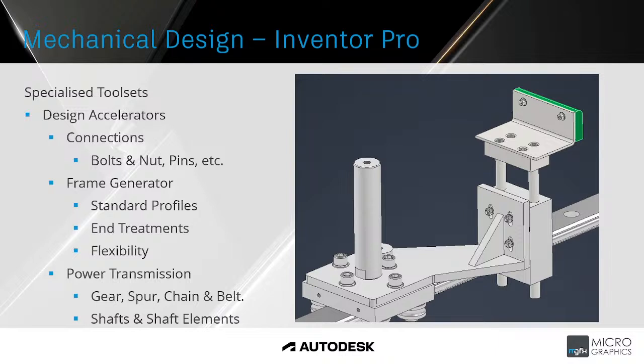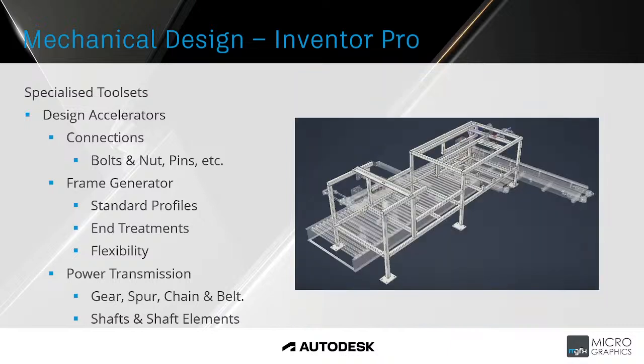And with the design accelerators, creating bolted connections like this is a process that is somewhat automated. You would go ahead and select the 4 holes where you want to place the bolts. You select your start plane, your end plane, and you then choose the hardware that should be placed in. That process of choosing the hardware can also be saved as a template. So the next time you add in a bolted connection, you can just choose the template, saves you from having to specify the hardware every time. And so it would be quick and easy to create these connections using that design accelerator. And the same goes to say for creating framework as well.